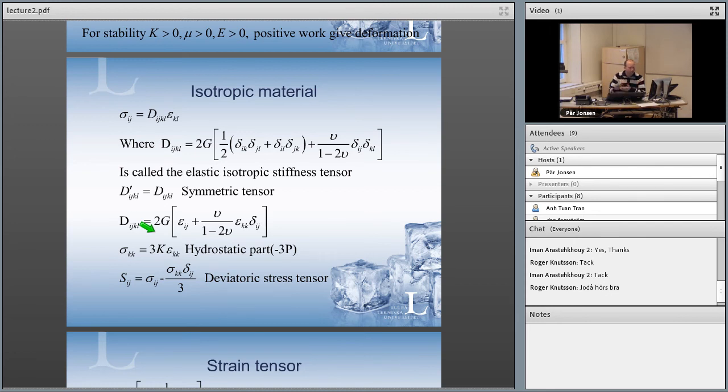That is a good thing. And also you can find the full deviatoric stress tensor by taking the difference, taking away the trace of your stress tensor with this relation. You will directly find, as you saw also in the lecture notes last time, I showed you that this relation is true.